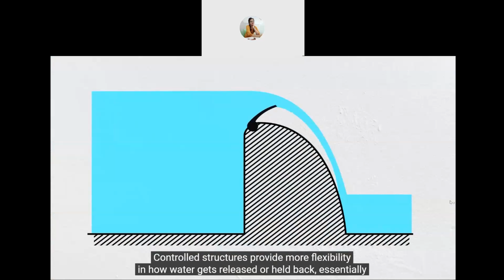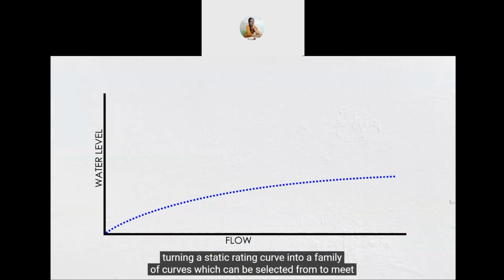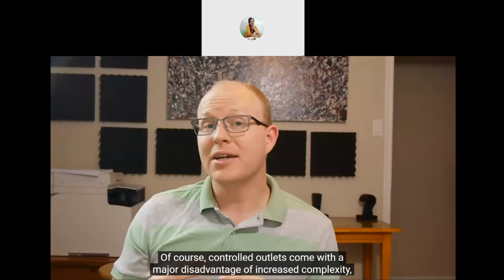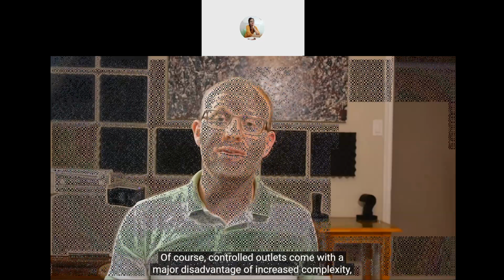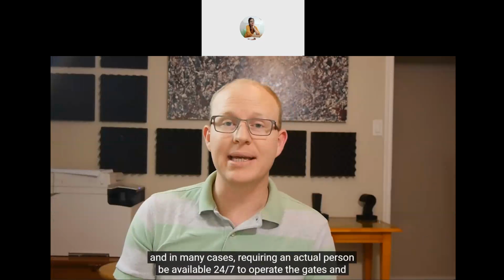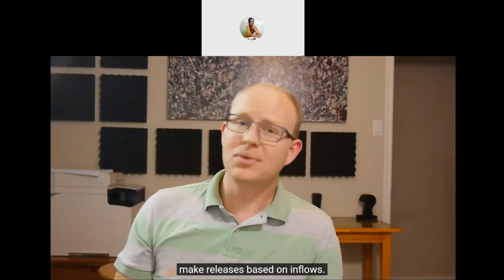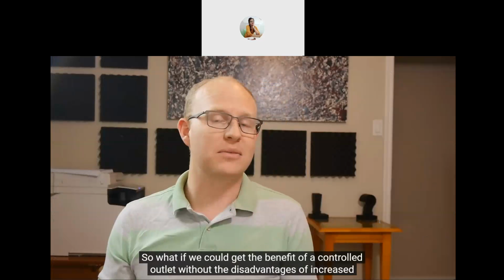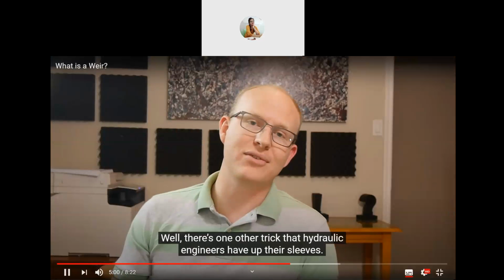Controlled structures provide more flexibility in how water gets released or held back, essentially turning a static rating curve into a family of curves that can be selected from to meet operational goals. Of course, controlled outlets come with a major disadvantage of increased complexity, and in many cases, requiring an actual person be available 24/7 to open gates and make releases based on inflows. So what if we could get the benefit of a controlled outlet without the disadvantages of increased complexity and operational obligation? Well, there's one more trick that hydraulic engineers have up their sleeves.